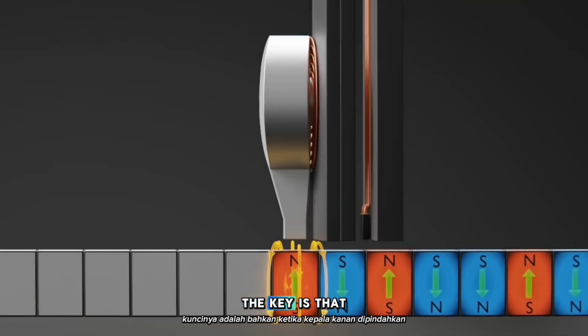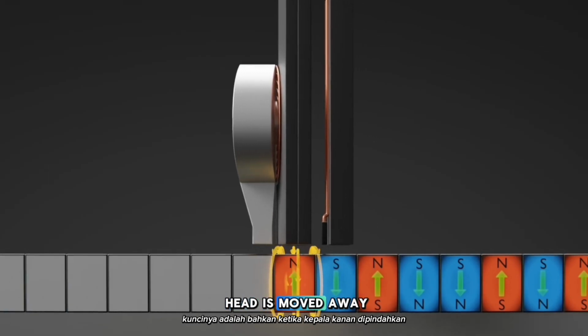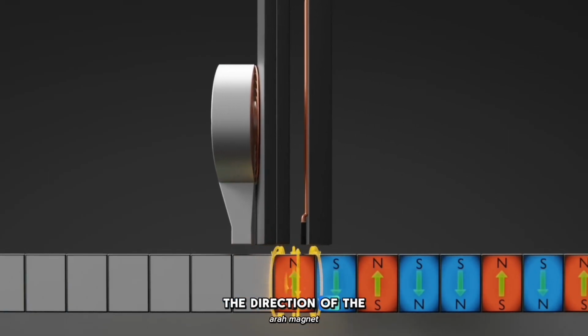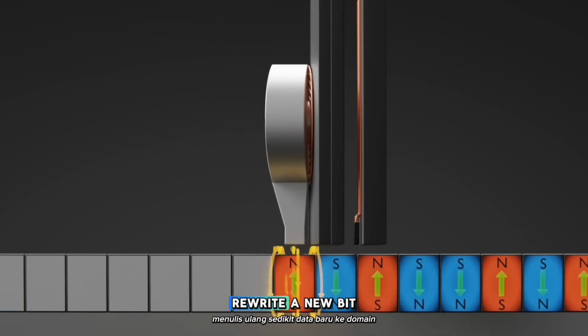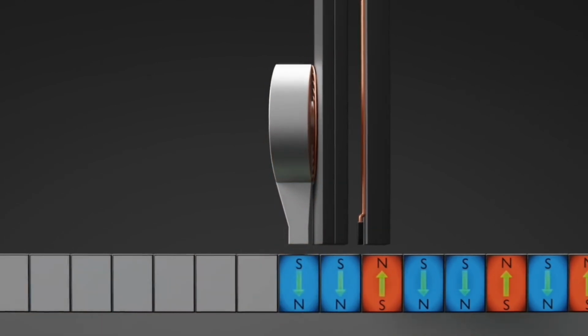The key is that even when the write head is moved away, the direction of the magnetic domain in this layer of the disk is maintained for years, and it emits a permanent magnetic field which can be repeatedly sensed by the read head every time you read out the data stored in this sector. That is, of course, until the computer and write head rewrite a new bit of data to the domain by either flipping the direction or keeping it the same.